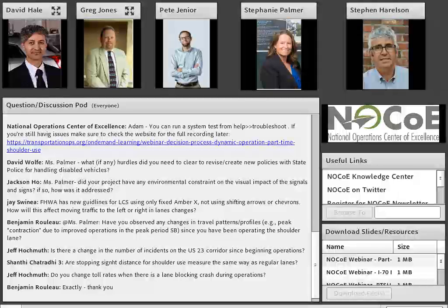Okay, thanks a lot. I've got now one question for Stephen, followed by possibly up to 4 questions for anyone on the panel. So the question for Stephen is, do you change the toll rates when there's a lane blocking crash during operations? Yes, we do. And in fact, we've even done it on a weekday when it was not in operation. We will open the peak period shoulder and charge a 0 toll just to, once the crash is cleared, if we've got 3 miles of backed up traffic, we'll open it up to drain it that much quicker.